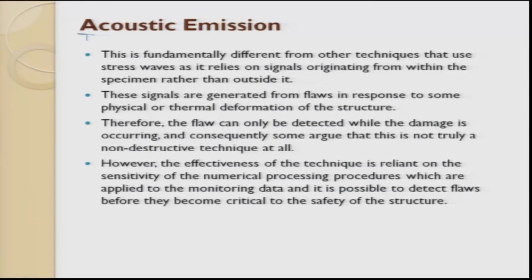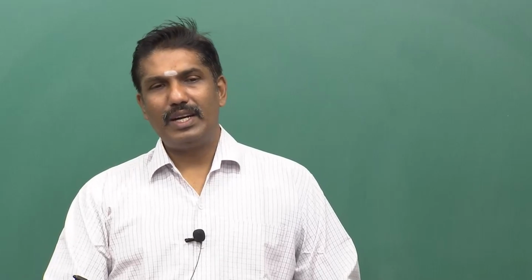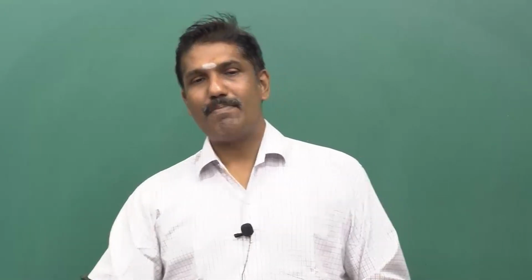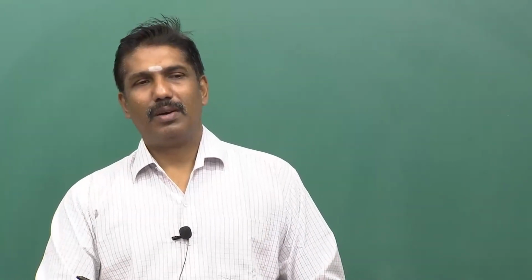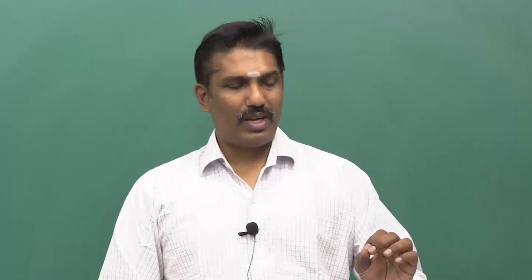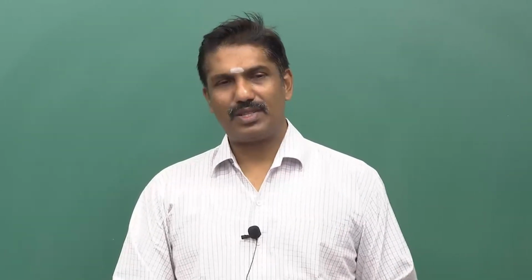The next technique is acoustic emission. Acoustic emission is also a non-contact type of non-destructive testing. Here what happens is I try to measure the stress waves which are getting released from the sample. For example, you take any plastic cover. When you start folding or unfolding it, it produces some sound, and this sound is called the stress waves. If I put a sensor and capture all these stress waves, I will be in a position to interpret and say what the defect is or what is happening to the material.